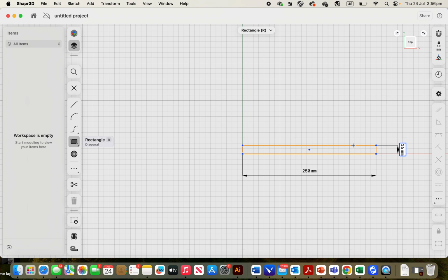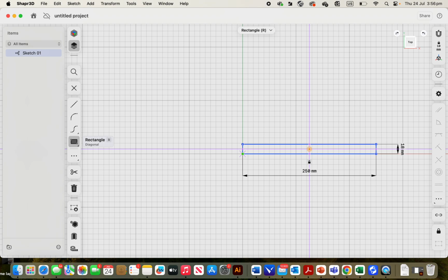What we need to do now is set the thickness of our timber. It's currently at 16 millimetres. Now this one I can come out by 1 millimetre at a time, but again, if it's kind of bouncing around, not really landing on the number I want, I can just type 18, which is what I want, and press return, and it'll snap to it.